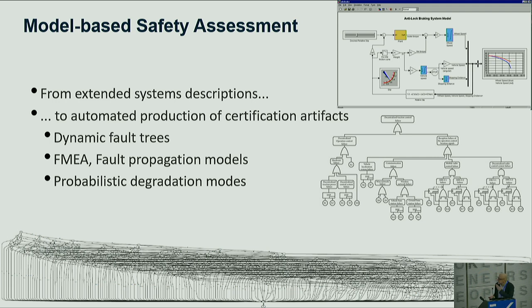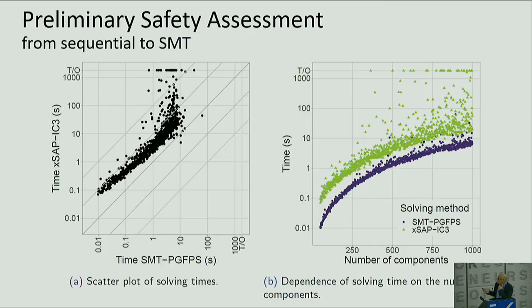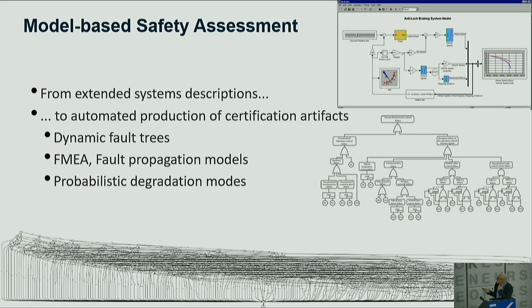Another important point is the ability to analyze complex systems under fault. Given a certain model of the system, which could come from a Simulink specification, we wanted to understand what are the possible configurations that will bring the system to a bad state, will cause a so-called feared event. And these elements here are so-called fault trees that describe all the possible ways in which the system could fail.